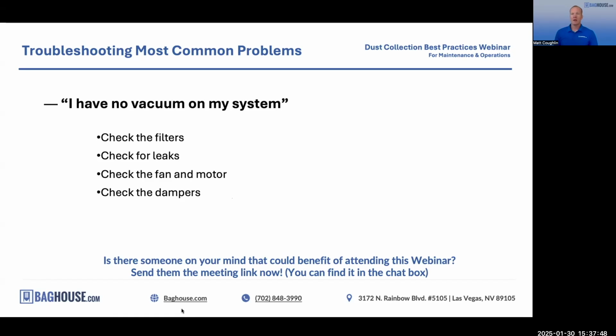And how do we do that? We go look at the differential pressure gauge in the bag house. So every collector should have a DP gauge or a magnehelic gauge or a differential pressure gauge, all the same thing, right? It'll just tell you what that static or differential pressure is across your filter. So brand new set of filters, maybe at 1 or below 1 inch water is the unit most often used. As the filters get packed with dust that will creep up to 2, 3, 4, 5 inches. And at some point, your filter cleaning system will kick on, blast it with compressed air or shake it, depending on your system. Whatever it is, it should knock the dust off. Static pressure goes down. And it should basically go back to operating the way you want.